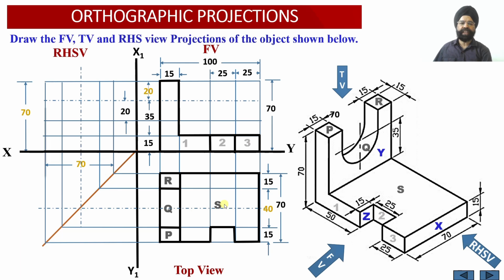Now let us draw the side view over there. In order to draw the right hand side view, two things we can observe, that is you can see this portion is visible, this portion is visible, slot over here in the vertical web. So the vertical wall, it is visible. Yes, please check this portion and this portion, they will appear as a straight line in the side view. Similarly, this portion and this portion, they will be appearing as a vertical edge in the side view.